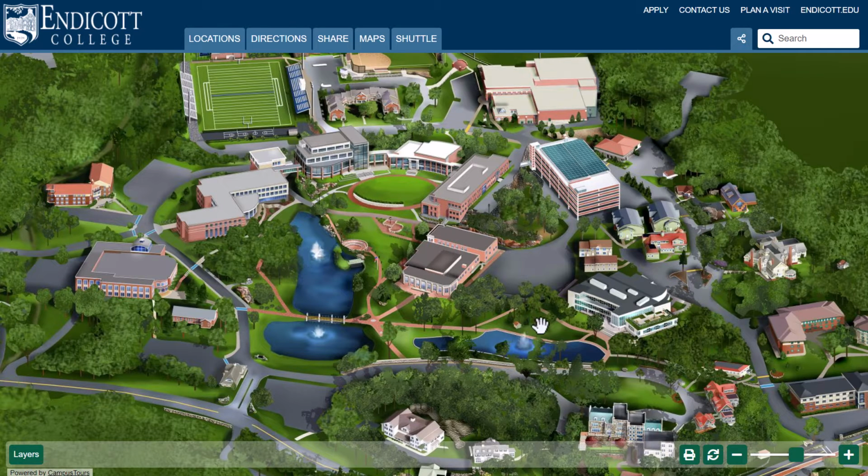And what you'll see on the site here is that the elements that Lumion can create really well are things like landscaping, trees, grass, all of the soft landscape design elements. The things that you probably should render or create in Revit are things like roads and parking lots, even things like playing fields. Those are best to model. Those hard architectural elements, those should be modeled in Revit.